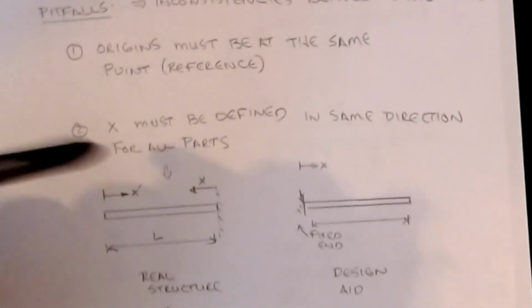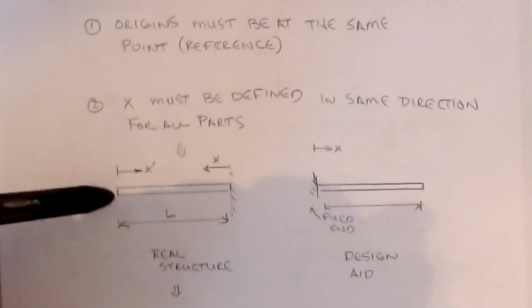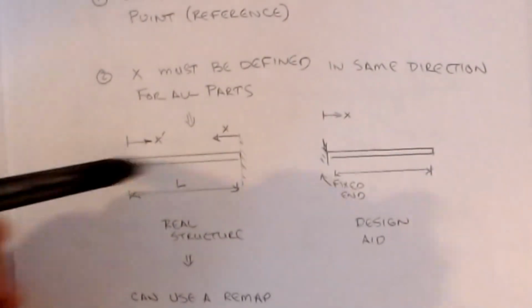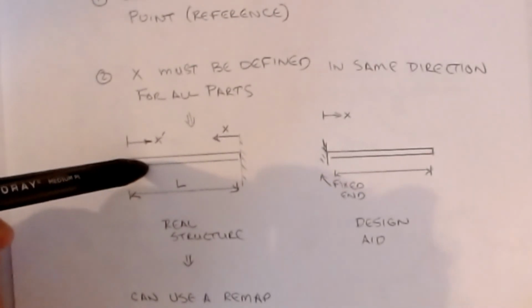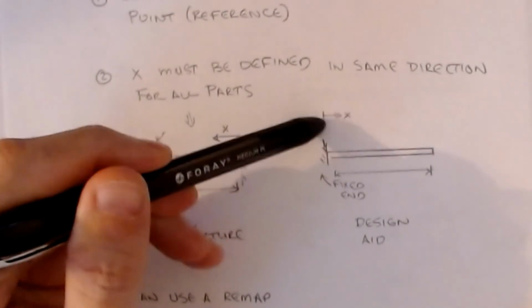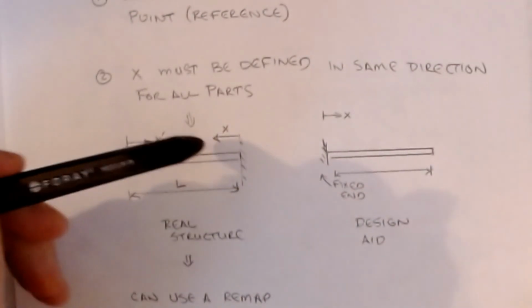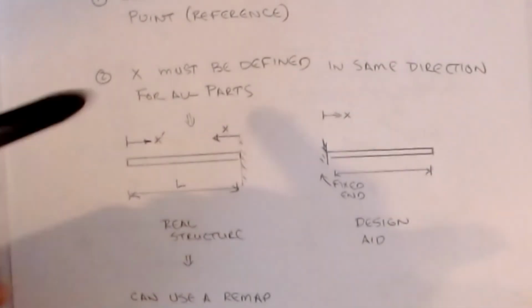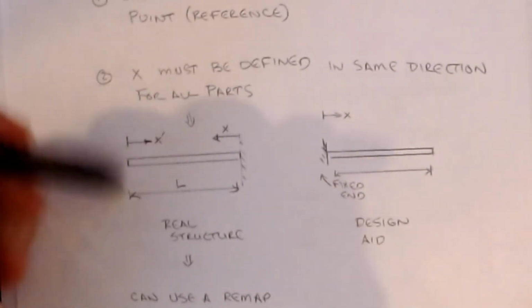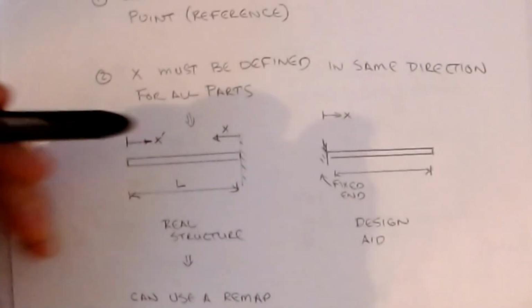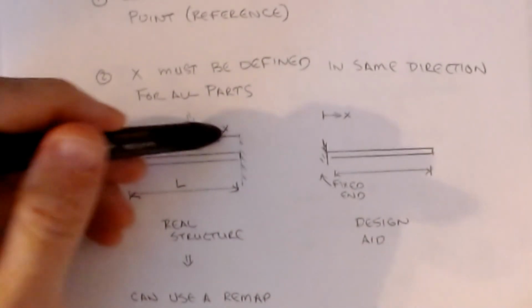One problem that's real common, and this shows up especially with regards to cantilevers, is that if I have a cantilever at the left end and fixed on the right, I don't have this case in the book. But what we can do is take the case from the design aid where x was measured from the wall or the fixed end to the right. On this picture, that would be like saying my x is measuring from here. And then if I need the left end, I can redefine my coordinate as an x prime from the left end as a function of this x value.